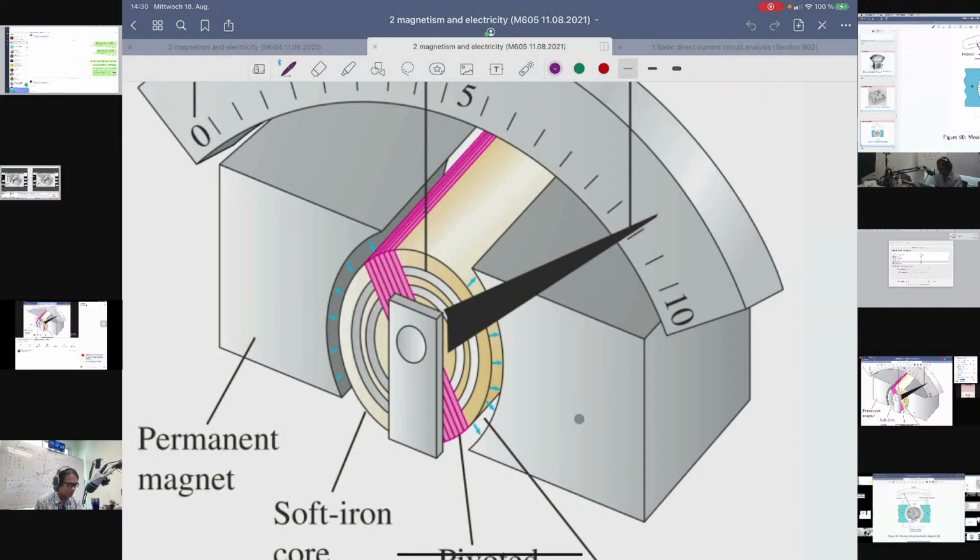That's the most favorite type of galvanometer used in that generation, or even nowadays. When there is a current in the coil, the magnetic field will exert a torque on the coil, and the torque will take place at the shaft, and it's going to deviate, or rotate, the needle from the original state, the zero position, to any bar here.